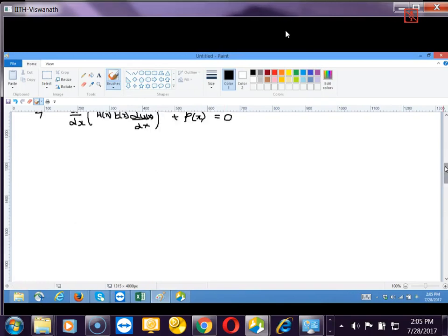So what we said was, if you look at the solution, this is u of x. The analytical solution can be some weird form from 0 to L. Then, depending upon the number of elements, a one element solution is like drawing a straight line between the nodes.